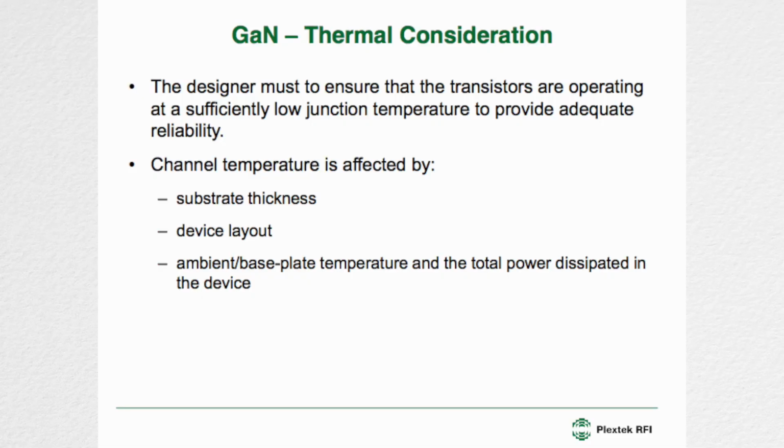A little bit more on thermal. It's the designer's responsibility to ensure that the transistors are operating at a low enough junction temperature to provide adequate reliability. Channel temperature is affected by the substrate thickness. This tends to be fixed, typically 100 microns.